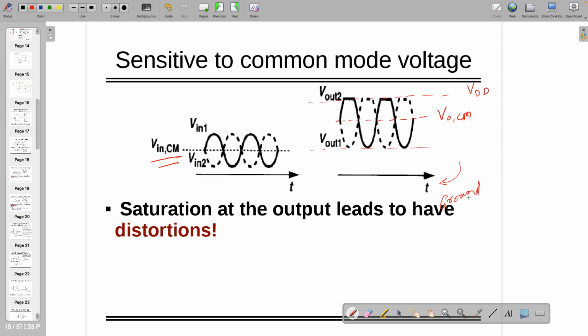Then you have to declare that one is a large signal. You have to control the input, give a small signal so that you can observe the output as required. You must have seen this kind of thing in your BJT circuit, or when you did the experiment in the laboratory, that it is getting saturated. This is happening because of the output common mode or the common mode gain. So this is called common mode gain.